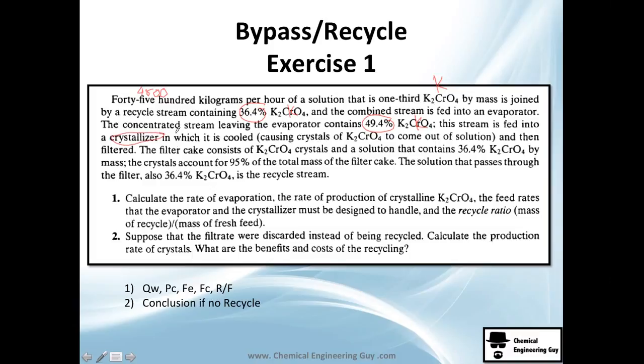Okay, we have a crystallizer, which is cooled, causing crystals to come out of the solution. Crystals mean solids, so guys, we're going to work with solids. Take care. And then the mass, the crystal count. This is super important. Crystals count for 95% of the total of the filter cake. What's a filter cake? Filter cake is simply the solid part of the filtration. The solution that passes through the filter is also, okay, another concentration of K, same as the recycle. Of course, they need to be the same because it's the same product.